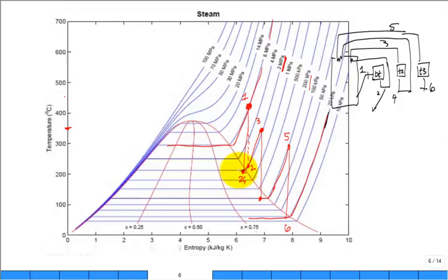All right, so now, same thing, if I had a little irreversibilities, isentropic efficiency, same thing. It would shift those locations of those states. But now we're going into the condenser. And what state comes out of the condenser? 7. And it's saturated liquid at that low pressure. So where is state 7?